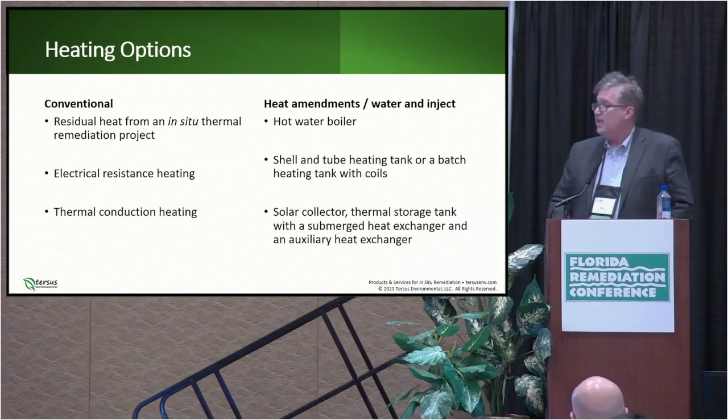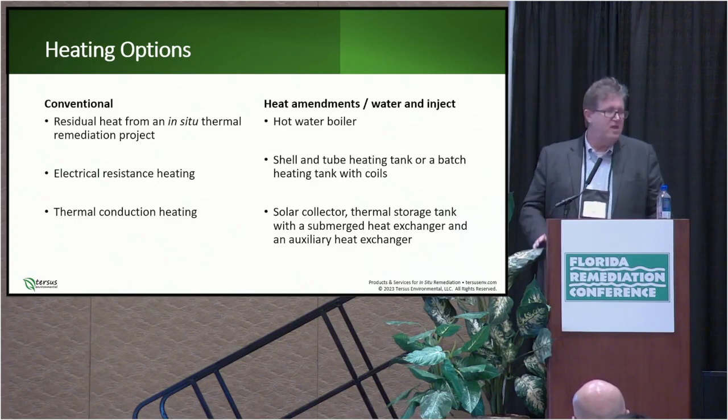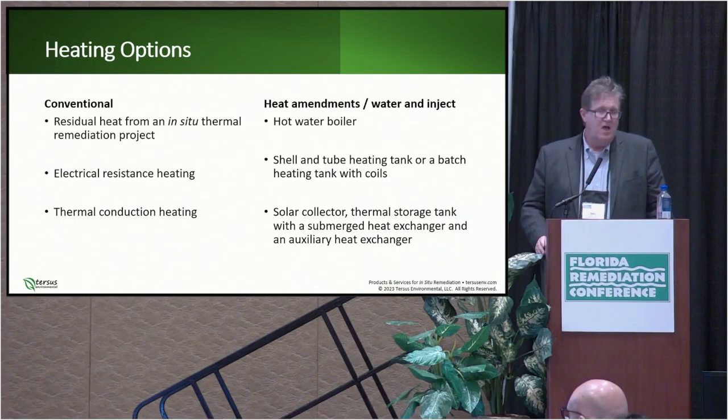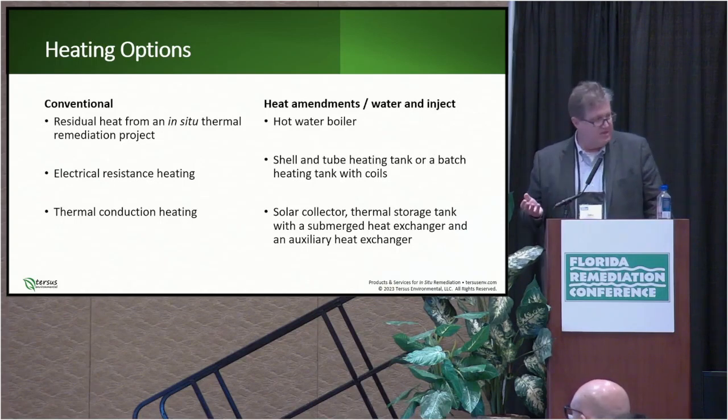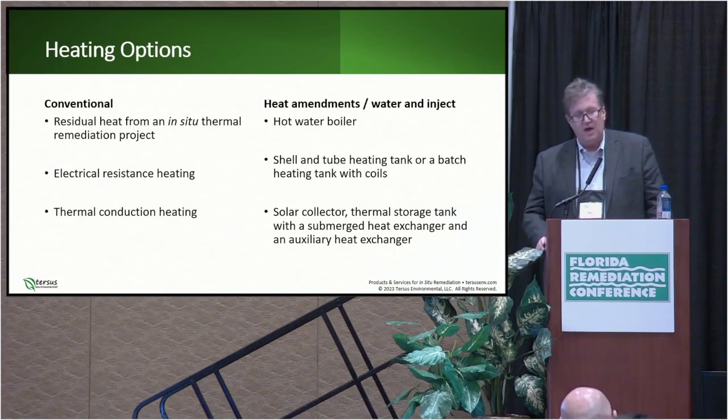So heating options, conventional, we've got in-situ thermal, and I would encourage you that, if you're doing a project and you're looking at doing electrical resistance heating or thermal conductive heating, that you go ahead and place some donor down gradient, because you're putting a lot of energy into that system anyhow, and so that energy is there to already heat that aquifer, and it's just a great opportunity to take advantage of it.